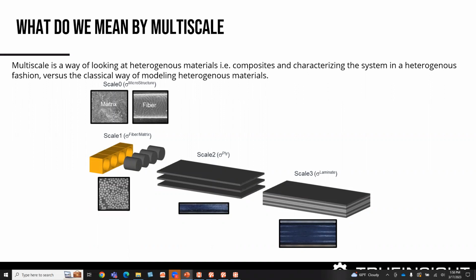So if you actually look at the microstructure here, it's not a uniform X, Y, Z, like this is what your Young's modulus is going to be in the X and the Y and the Z. It's really very different, and material scientists have been aware of this. If you're doing composite design and composite structural analysis, the classical approach was you'd always have to iterate and make sure your FEA results matched experimental solving. So it could be, I don't want to say tedious, but maybe more labor intensive.